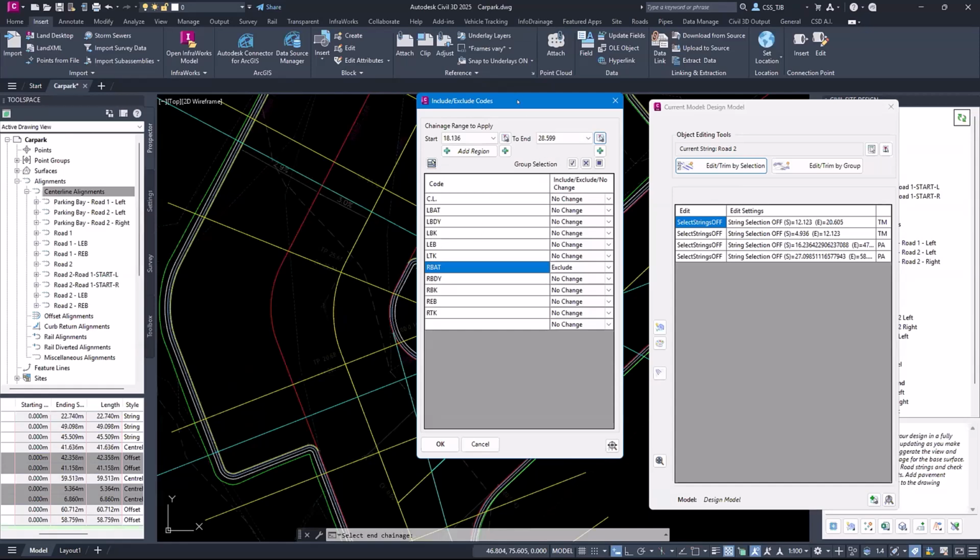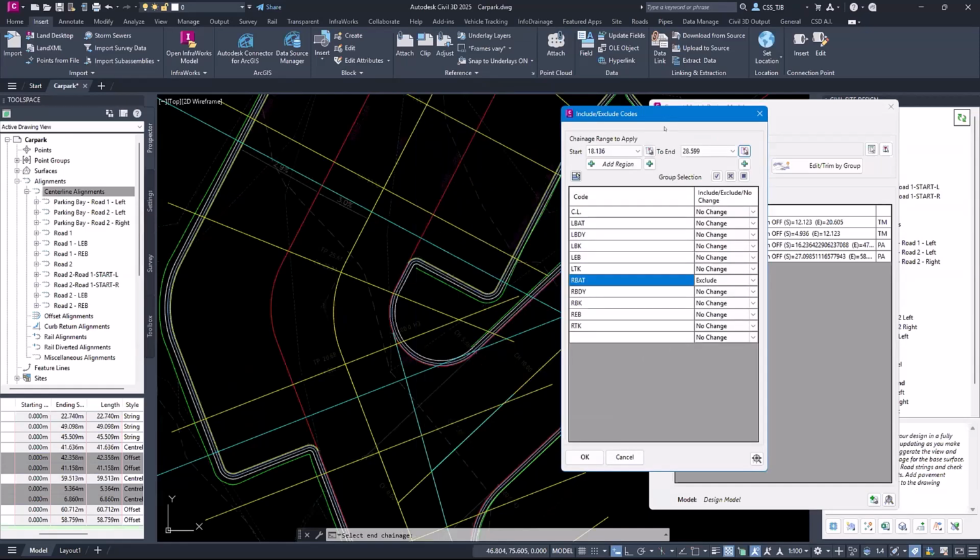Now, little side note. It's been in the software for a little bit, but it's something that's probably not overly exposed. If I needed to add in a sample point I wanted to use for my model that didn't exist in my sampling regime, which is the stuff sitting here, you can actually use these add regions buttons. So add region allows me to add a start and an end. This one allows me to add just a start. This one allows me to add an end. So it basically opens up the insert sections command and allows me to add in my own values at the time of doing the edits. So if you haven't played with those things when you're in this part of the software, have a go at it. It's actually really cool.